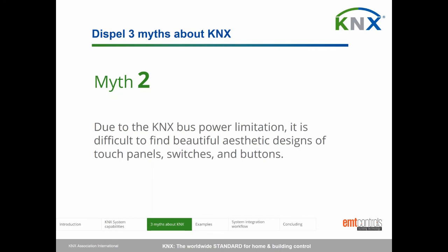As we know, normally KNX devices take their power from the KNX bus. That's why the goal of the manufacturers of KNX products is to make devices consume minimal power. KNX power supplies are limited in their possibilities, and KNX modules inside of the device can't provide a big current, so the bus is not capable of driving big loads or a big amount of devices without special hardware elements.